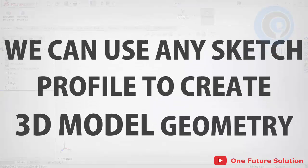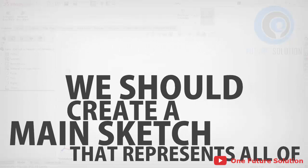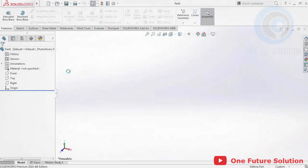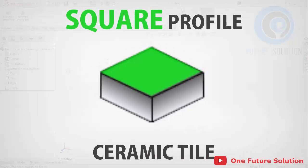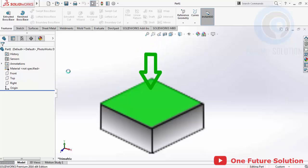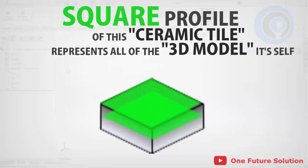Actually, we can use any sketch profile to create a 3D model as we want, but to get better results, we should create a main sketch that represents all of the 3D model itself, or a sketch profile that will produce the major body of a 3D model. A simple example is when we create a 3D model of a ceramic tile. As we know, a ceramic tile has a square profile as a main body. So, if we design the ceramic tile in SolidWorks, we should create the square sketch geometry first, because the square profile of the ceramic tile represents all of the 3D model itself.